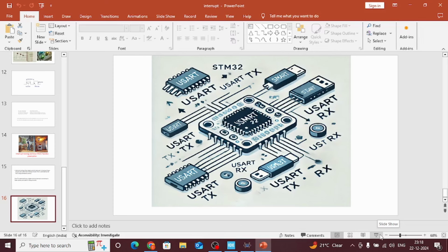fixed baud rate. Baud rate is a rate of interval, which means both transmitter and receiver should agree on the same value, and only then will you have effective communication. Because now the transmitter knows that the baud rate is 9600, so I have to send my message with this interval only. Each byte should have this much interval. And also we have the frame sequence, so now the receiver can easily understand the message, because the receiver knows that first one bit means start bit, then 8 data bits are there, then one stop bit is there.